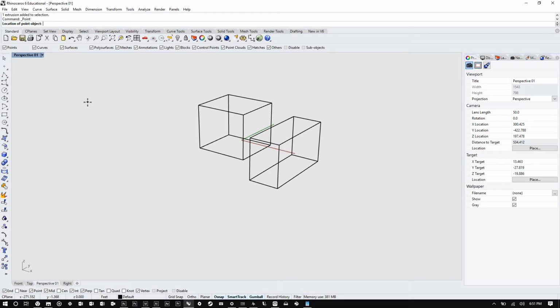Your point tool, which creates a point, which is pretty handy. If you click on the down arrow, you'll see other options for points. If you want to place multiple points at the same time without having to reinitiate the command, that's under the point command. So now I can place as many points as I want. And I'm going to get through this pretty quickly.